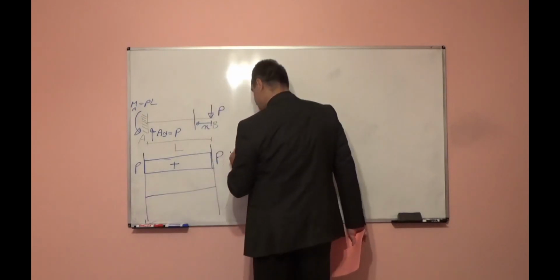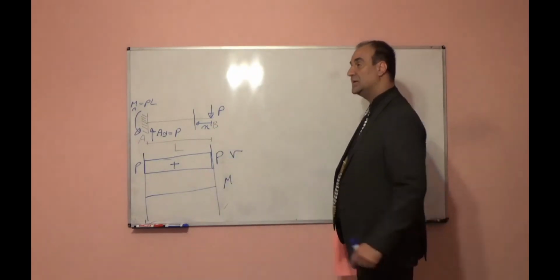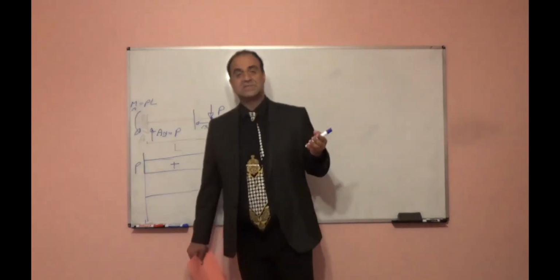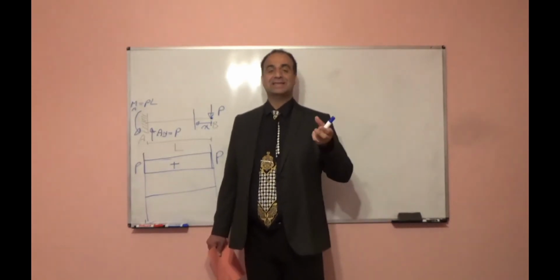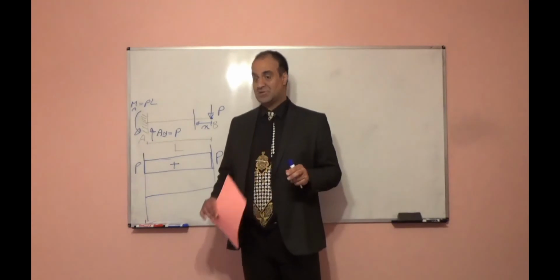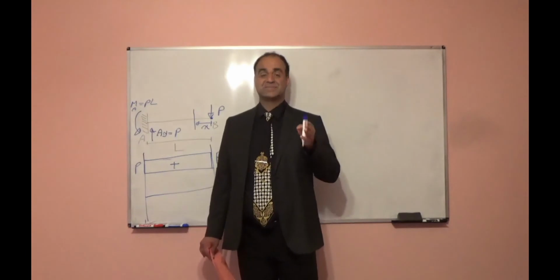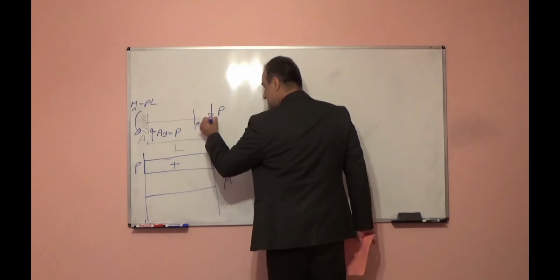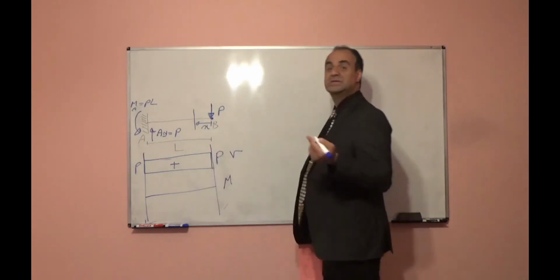Bending moment. At point B, it is a free end. What is the moment? Moment means force times distance, tendency of rotation. At point B, we have force, but there is no distance between point B and B. So P exactly is at point B, and the distance from point B is equal to 0.